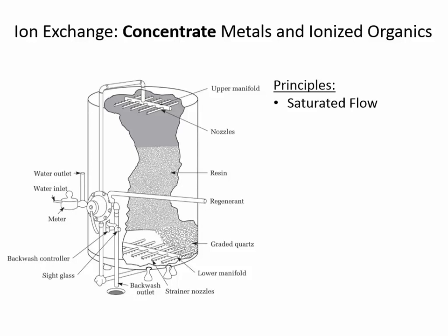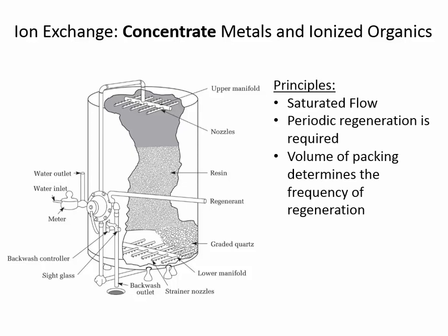And so the removal of heavy metals can sometimes be accomplished by directing the water through the top of a column like this that's packed with the special media or packed with the resin. And over time, this resin can absorb a certain amount of the metal, but then it's going to lose its effectiveness. And so now what we have is this column that's loaded with the pollutant. And so the pollutant has been concentrated, and it has to be regenerated. We have to somehow flush this column. We have to rinse off the beads that are in there and increase its ability to absorb the pollutant again.